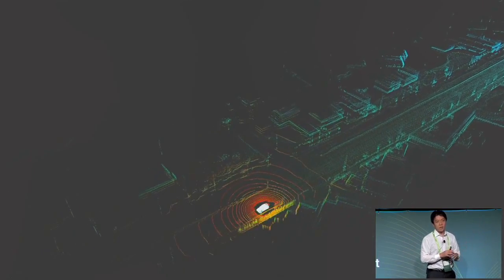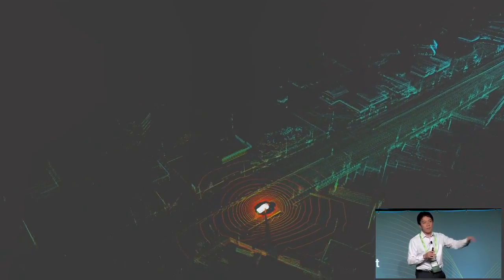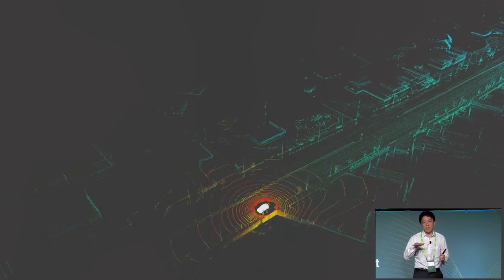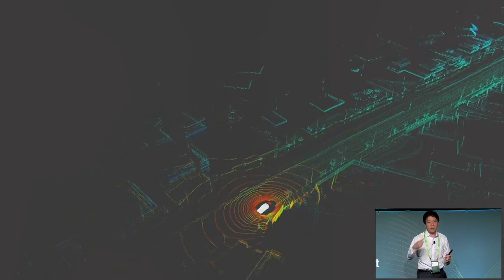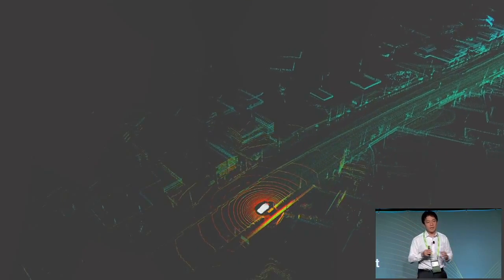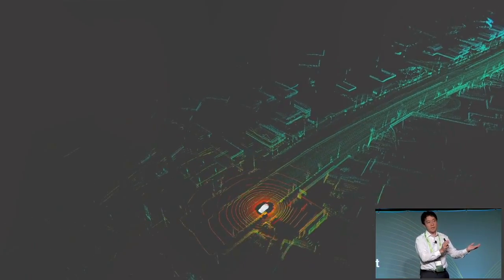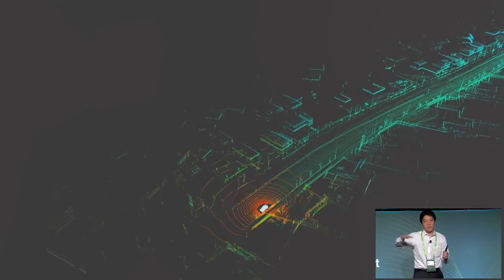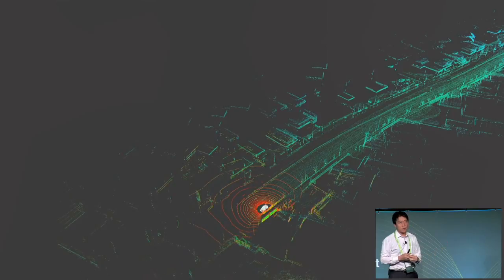So this car ahead, you don't have any map data, but because the car now has localization performed, it keeps saving the scan data. The car itself has a laser scan sensor, so if the car goes to some place, the shape of this place can be saved. Accumulating these scans, we can finally acquire the 3D map information. So if you have Autoware, you can also build a rough 3D map.